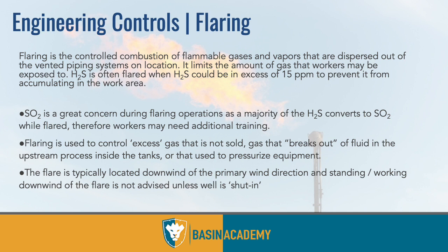So again, flaring is one great engineering control, where essentially we take any excess gas and send it to the flare. That typically goes through the treater, and then the excess gas is sent to the flare. Depending on the system, this may be more or less effective. If it's designed really well, it's very effective because you can even send the tank vapors to the flare, which Continental has done successfully in a lot of their wells and others.